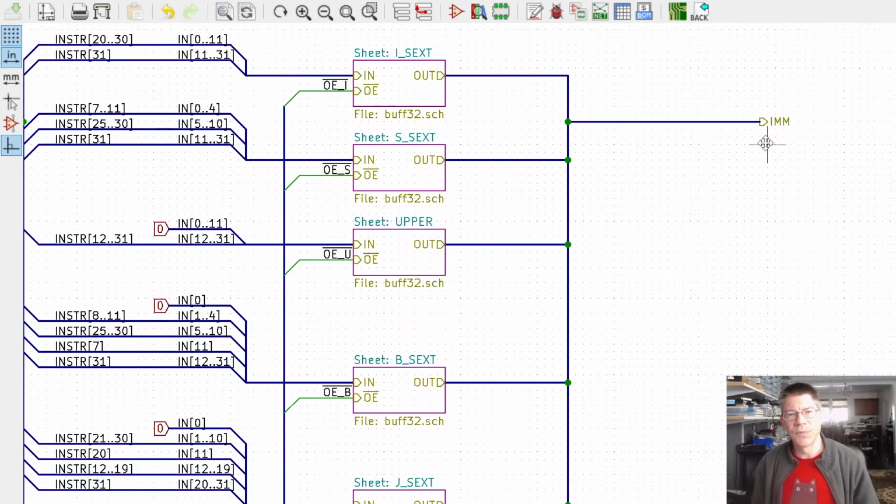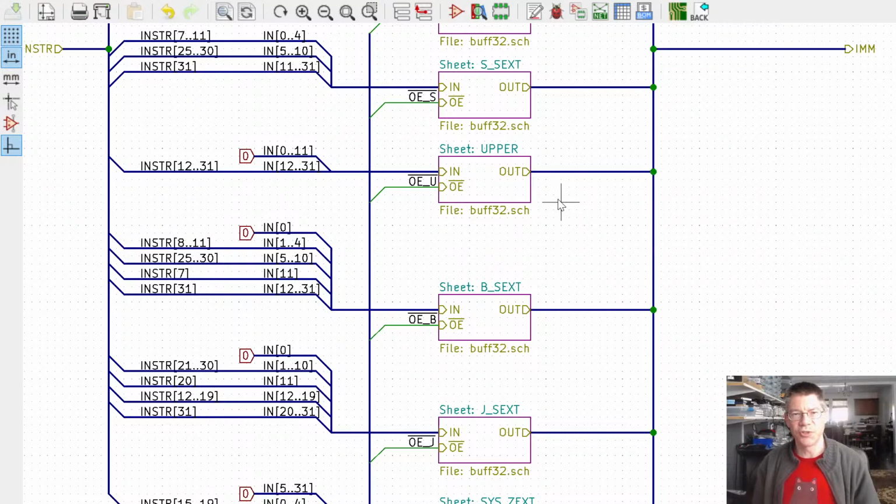Because the thing about modern CMOS and even TTL is that if you have an input, you need to make sure that the input is not high impedance, that it has a specific logic value. Otherwise, the input internal to the chip is going to float to some halfway value, and it's going to burn a lot of current. So if you ever run into a situation where it's possible for a bus line not to be driven, and that bus line goes to some inputs, make sure that you put pull-up or pull-down resistors on them. All right.